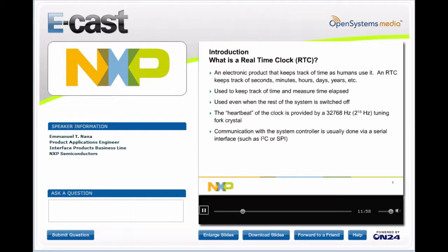And then there's a clock output also that can output either a 32 kilohertz or there is a divider register within the device, and the user can program that register depending on the frequency of interest. Then they can get the desired frequency at that clock output, and then there's a clock enable also tied to it. There is also one feature that's in this device that is really of importance, and I want to highlight that, and that's the electronic tuning feature. So on the next slide, I want to focus more on that electronic tuning feature, which is also available in the PCF2123.